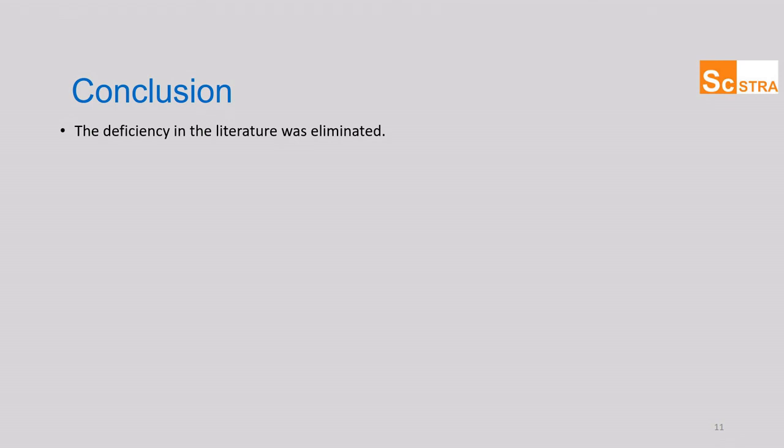The waves were produced by the wave generator, and with the help of a ramp, the broken or unbroken waves affect the head section. Consequently, it was observed that scour reduced significantly in the broken wave case compared to the unbroken case.